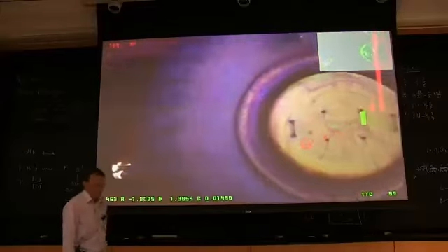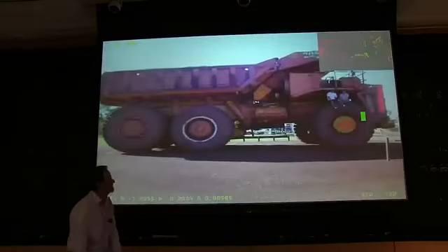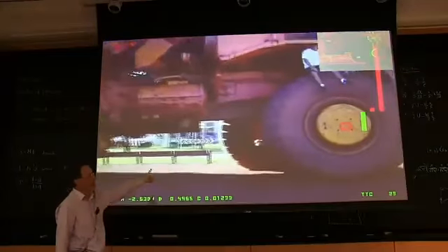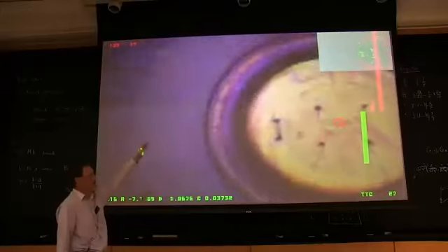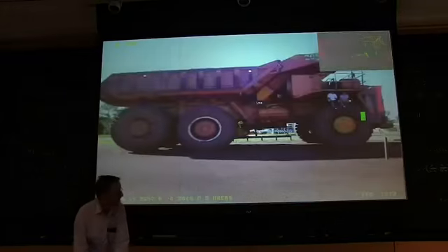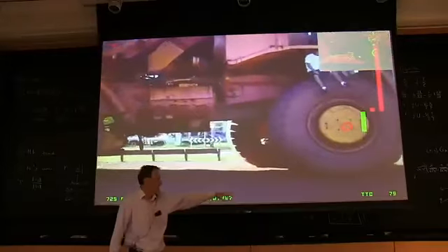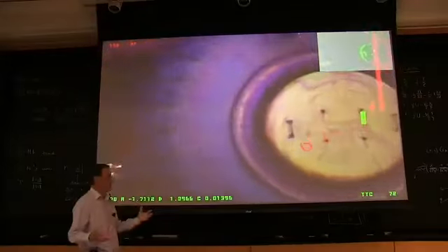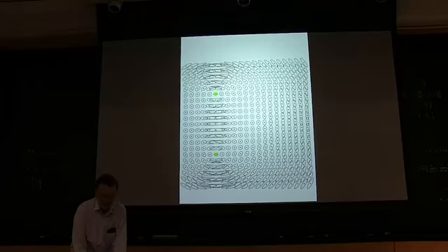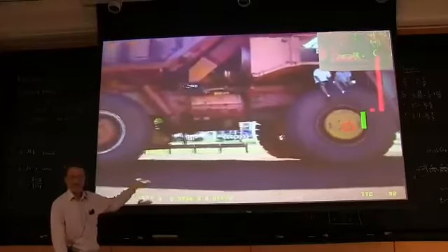And then you will see the 3 bars on the right. So the third one is C, the thing we just calculated. And you can see that it's red, meaning bad, and it's growing upwards as we approach. It's the inverse of the time to contact. And there are things like the time to contact is over there in frames. And we can plot to see how accurate it is compared to when we actually hit that target. So this is slightly different from what we did because this allows some motion in the X and the Y direction. And we'll do that in a second.